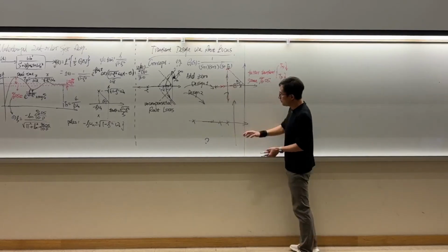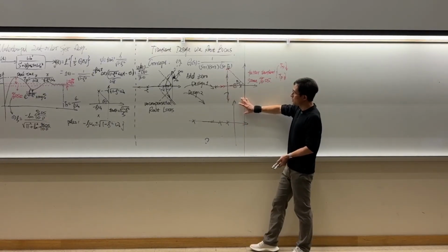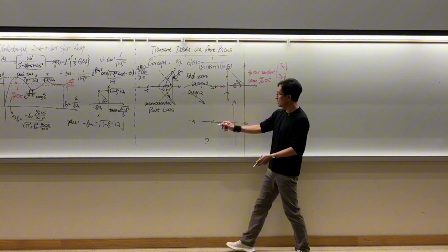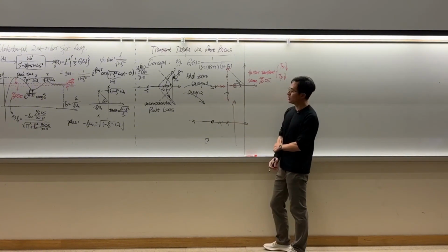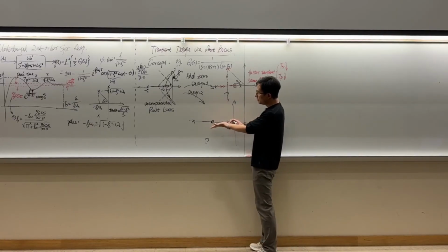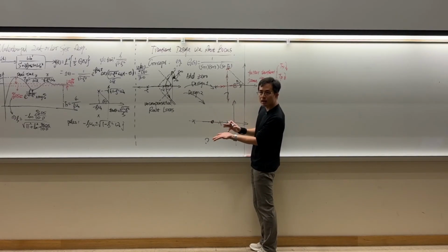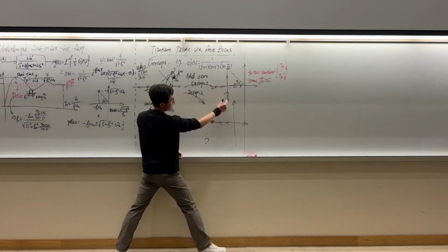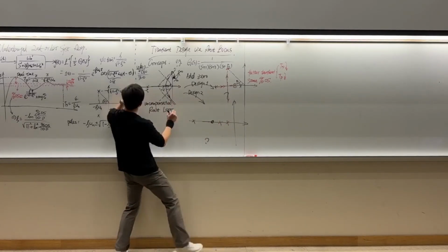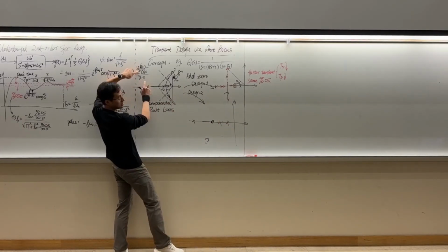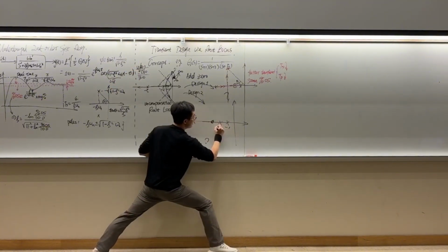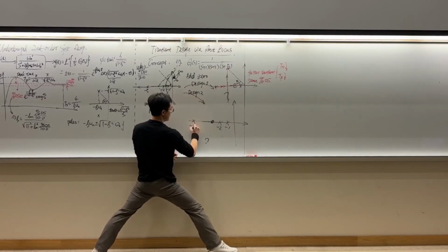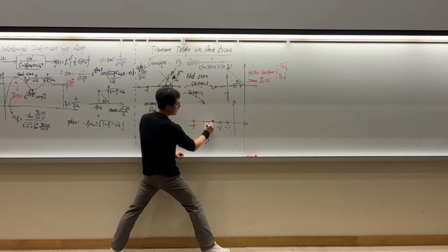Let's reinforce the understanding and observation using a second example. If your 0 is added a little bit more to the left, let's see what happens. Again, the asymptotic angle is still 90 degrees. It's this one divided by 3 minus 1, so it's still 90 degrees. The center location is going to be, so this is -1, -2, -5. Let's say this 0 is designed to be -3.